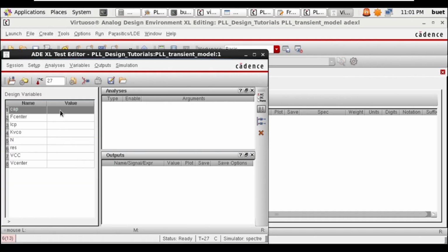So now, in the last class, if you have seen the video of the last class, there we finalized, or changed, capacitance C and charge pump current to adjust the bandwidth. So here we will use the same values. Capacitance C, which we have finalized as 35 pico, and the charge pump current ICP we decided was 26 micro to get 1.25 megahertz as bandwidth.